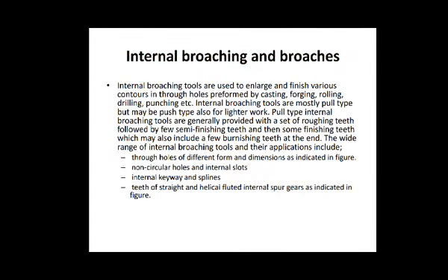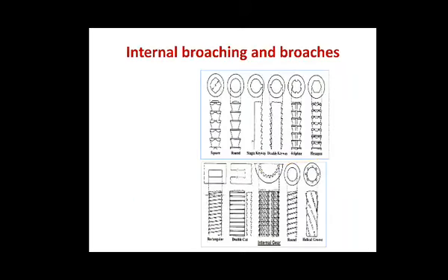So here internal broaching tools and their applications, which include internal keyways, splines, non-circular holes, and internal slots. Here you can see these broaches are used to get such shapes. This is what internal broaching is.